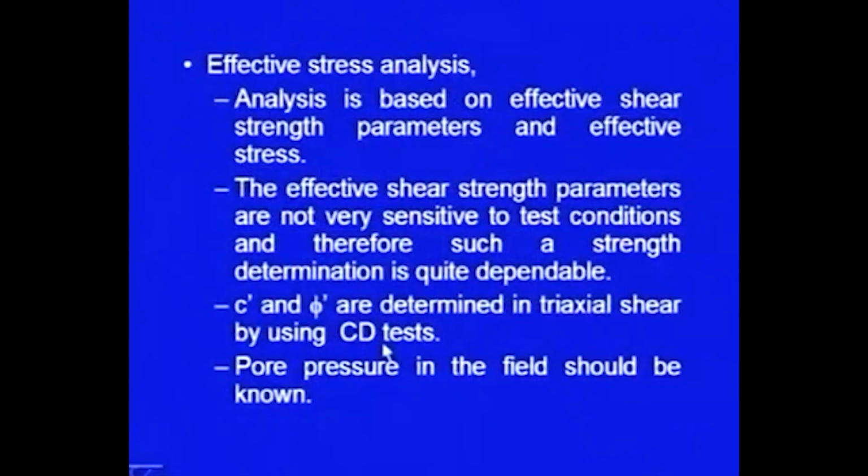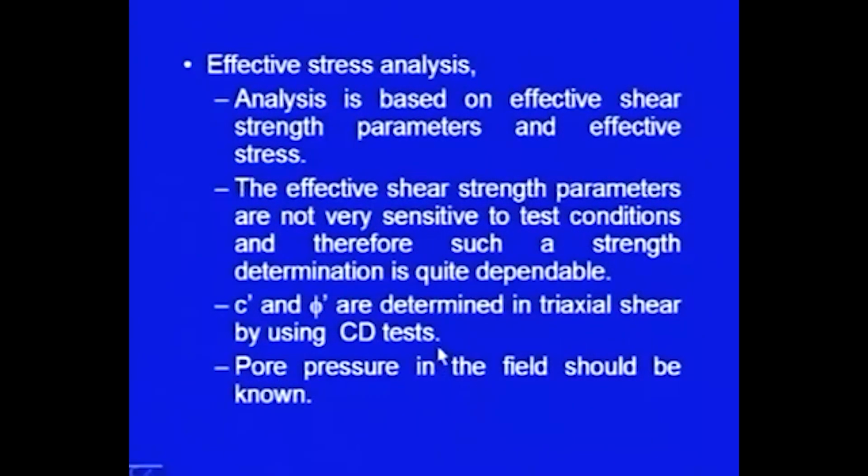c dash and phi dash are determined in the triaxial shear test by using the consolidated drained test. So, these tests are common. You can find out c dash and phi dash using the triaxial shear strength test by using the consolidated drained test. And for this analysis, because we are not assuming the pore water pressure to be simulated in the laboratory test values of the shear strength parameters, it is essential that in the field pore water pressure should be known. Then this effective stress analysis will be much more reliable.